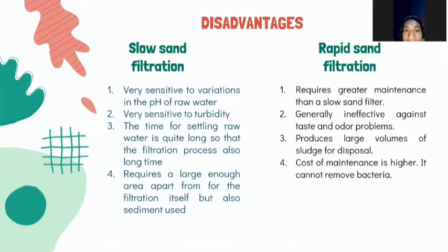Disadvantage: slow sand filtration is very sensitive to variation in the pH of raw water, and the rapid sand filtration requires greater maintenance than a slow sand filter. Next.